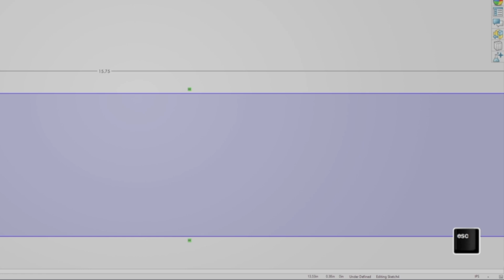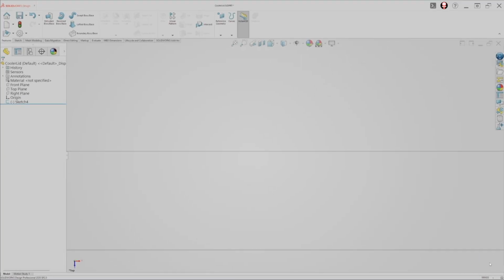So let me hide my escape key visual here so that I can show the units more clearly. We have different options here. Typically, I usually choose between millimeters and inches. For this case, we've been talking about millimeters, so let's go ahead and work in millimeters. I will click MMGS, and you can see it right there, MMGS. So that effectively changed the file to a metric file.